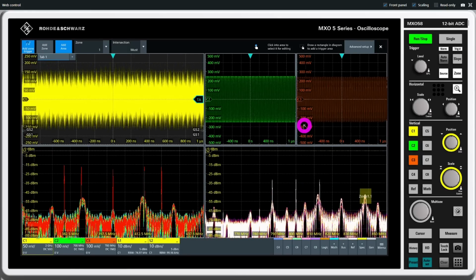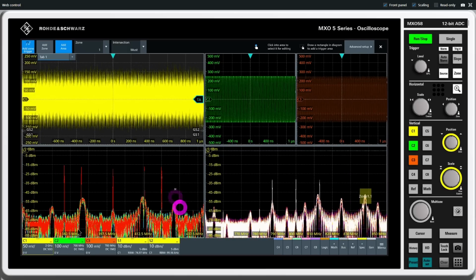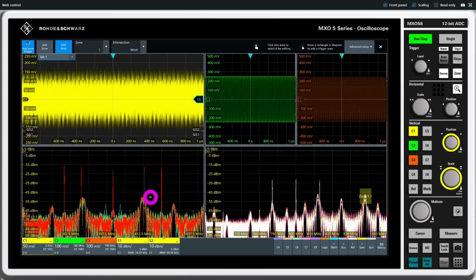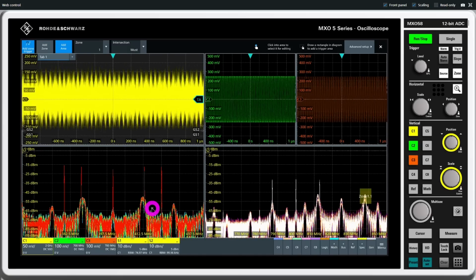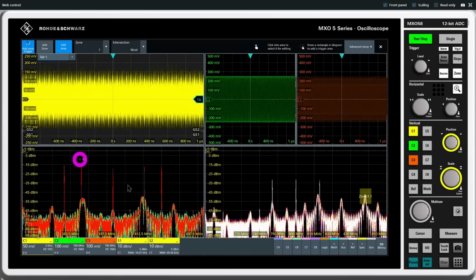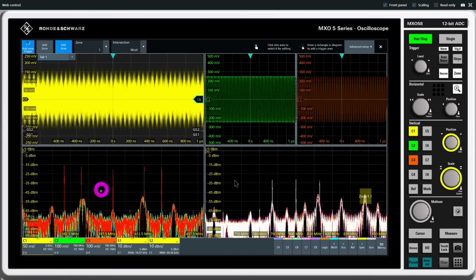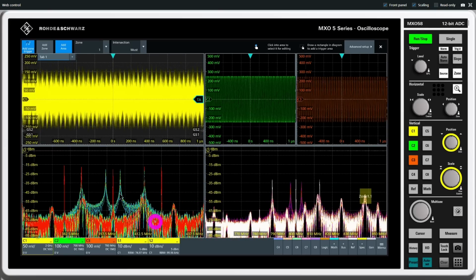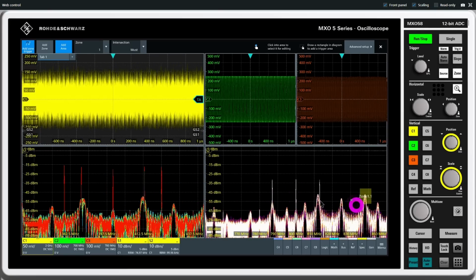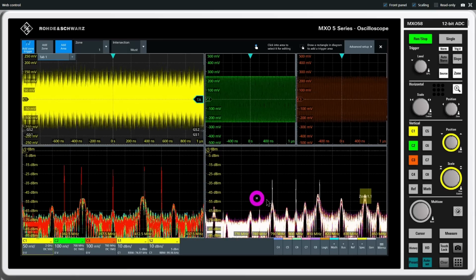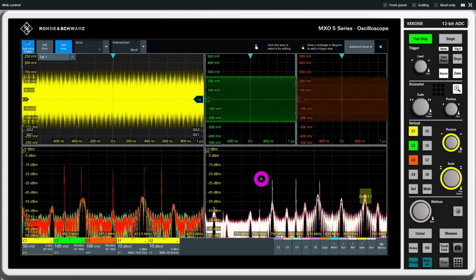Now, this gives us a critical piece of information, and that is that this signal is not correlated to the frequency of our frequency shift keying signal. That's a huge piece of information. Again, I'm not sure how else you would discover this, that these are not actually related to each other. It's pretty nice to be able to do all of this, but clearly they're interacting with each other in some way. That's another very nice way of finding unusual behavior in an RF domain.